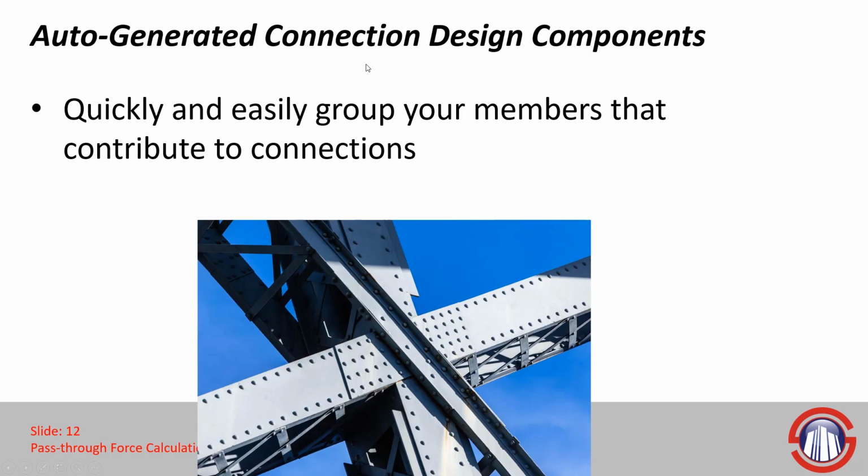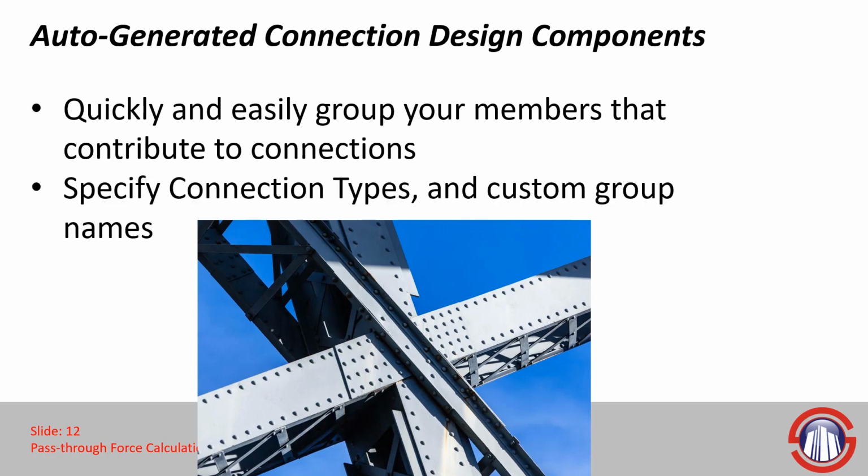And the advantage of using this approach versus the manual approach where we assign pass IDs to specific member ends is that this allows us to quickly and easily group our members in our entire model that would contribute to a specific connection. We can also specify connection types and custom group names if we wanted to.